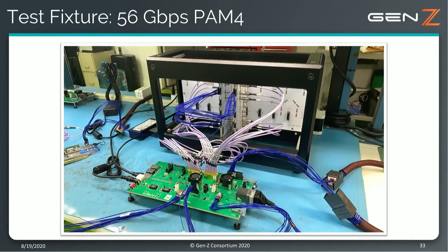In the background there, you can see the PCFF emulation platform, white Tachyon board, I think that's Tachyon, and a couple of riser cards. And in the foreground, you can see one of what we call our FAE demonstrator boards. That board, that green board, contains two Credo semiconductor Bald Eagle chips, two retimer chips, generating a total of 32 channels, in this case of PRBS 31 at 56 gigabits per second PAM4 data.